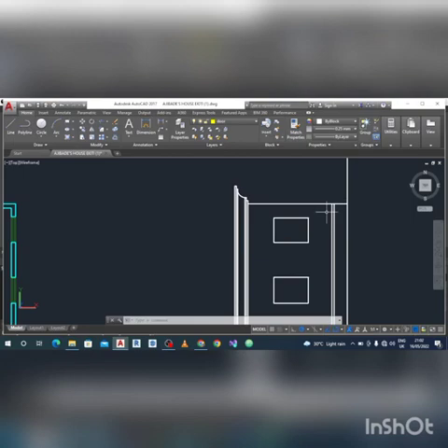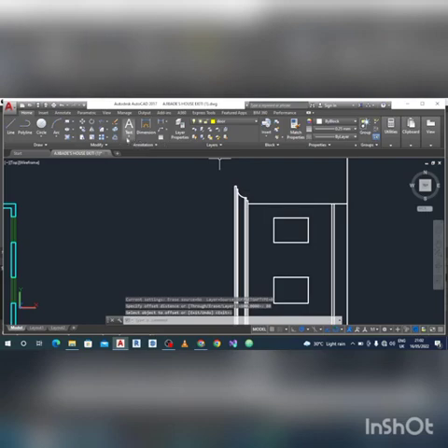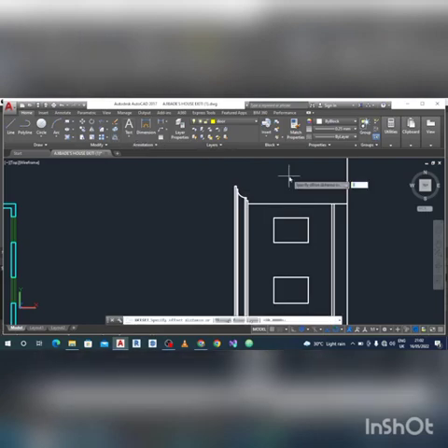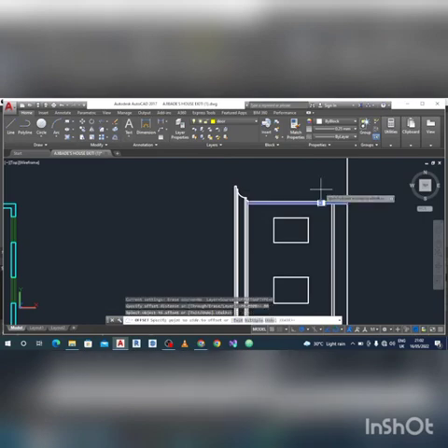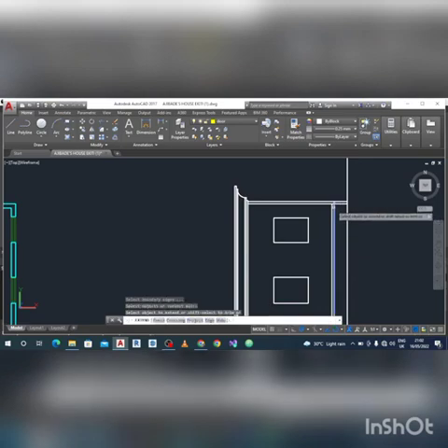That's offset 80, enter. Take note of, sorry, offset 80. Take note of this little adjustment that we're making. Then extend EX, enter. Yep, and yeah, so escape, and we zoom in.